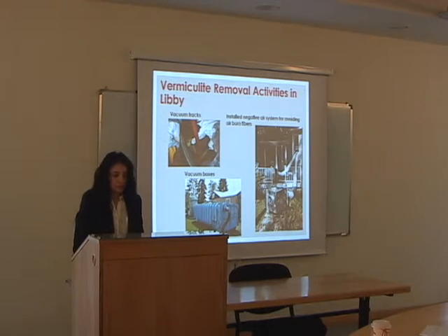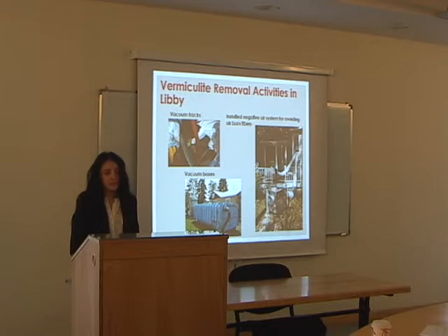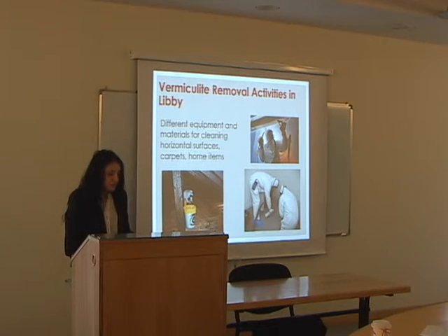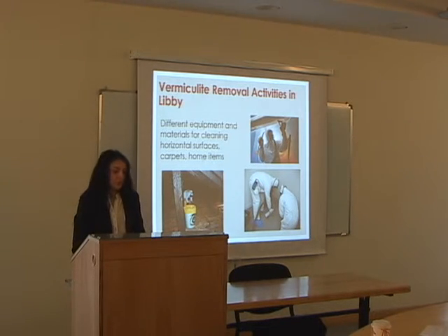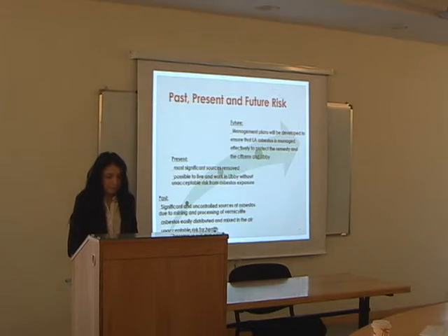For these activities, vacuum trucks and vacuum boxes were used, and a negative air system was installed to avoid airborne fibers. Different equipment and materials were used for cleaning, especially horizontal surfaces, carpets, and home items. And the progress is observable.